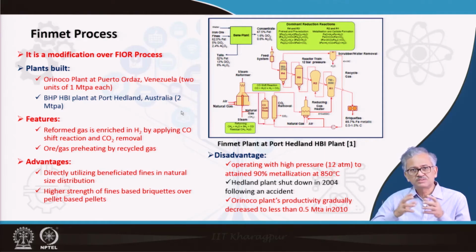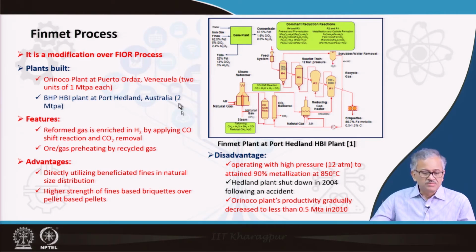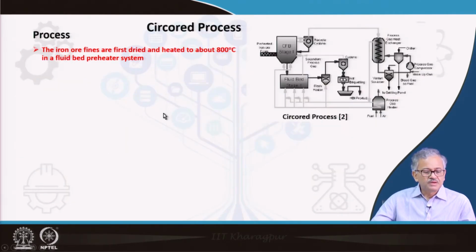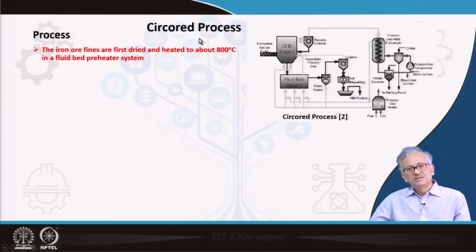Otherwise, the fluid bed, since it is in the fluid state, has another problem, the sticking problem. The particles try to stick, and finally they become agglomerates, and then finally the process shuts down, because the process doesn't work. They become bigger and then settle down. So this has two inherent problems. In spite of all these changes, some problems still remain, and also maintaining the high pressure is a problem.